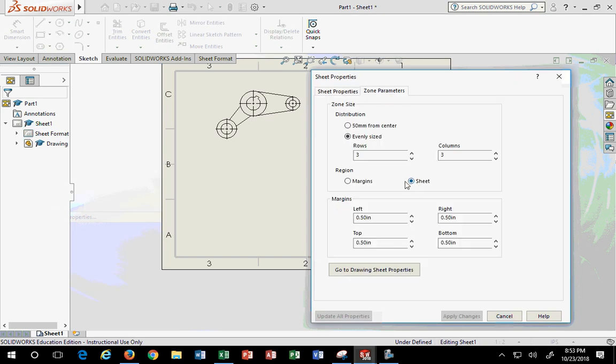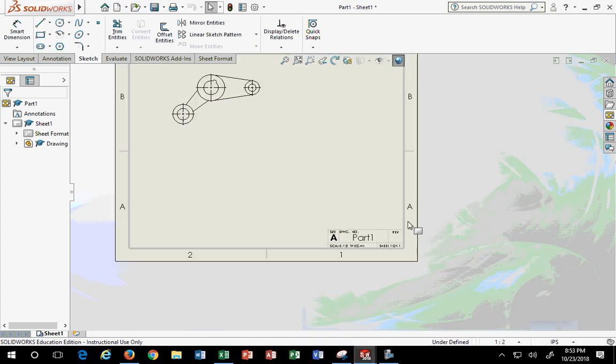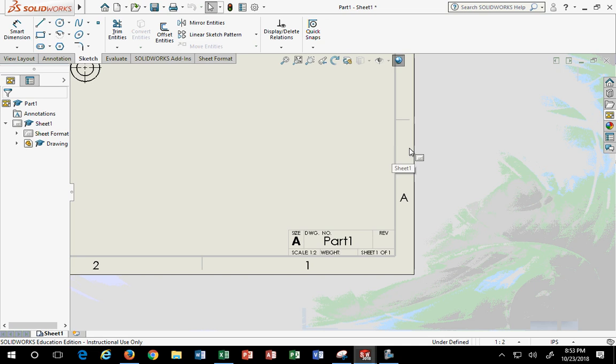When you do that though, you have to appreciate, you know, what am I going to set it to? I'll set it to 2 instead. You're going to appreciate that it's got all these extra parameters that you want to include. Margins, your margins are set predominantly by whatever your printer works with, so you end up making a custom everything in the real world for this thing, because their default ones are probably not ideal for what you're doing. I'm going to leave everything else alone, because this is a lot of lost real estate. This half inch there, that's a lot of lost real estate. You're losing an inch of space to draw in.